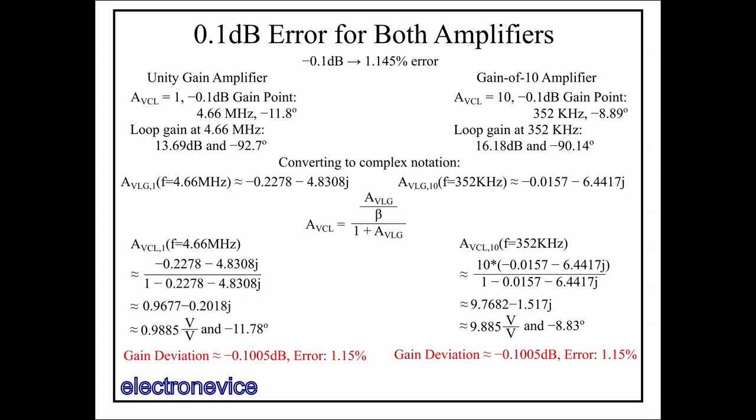So the equations we used to determine the deviation from the ideal op-amp gain using the real loop gain we learned in the previous episode are still valid. We just need to properly incorporate phase in order to perform those same calculations. Fortunately, phase shifts in the loop gain actually reduce the error in the closed loop gain magnitude. So if you ignore phase, you can overestimate the required loop gain for a given error value during your design phase.